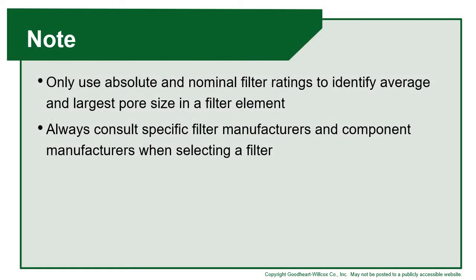As someone working in hydraulic systems, it's important to understand the difference between these absolute and nominal filtration ratings. Keep in mind, if you are looking at nominal ratings, there is the potential for larger contaminants to get through. If this is a major problem with your system, you want to make sure that you alter your filtration system.